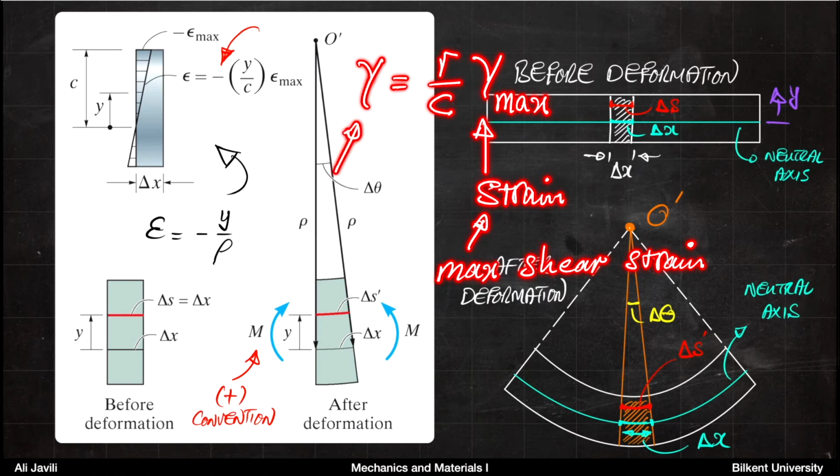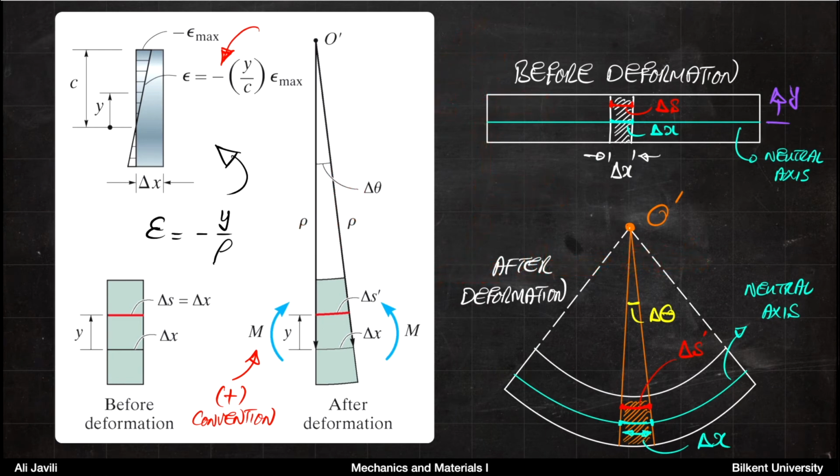And basically, you could assume also in a torsion problem that shear strain was a linear function which would go to 0 if r was 0. Here we talk about normal strains, not shear strains, and it goes to 0 at the neutral axis, and it can also be negative. So again, there are similarities between the bending problem and the torsion problem, and there are also differences.